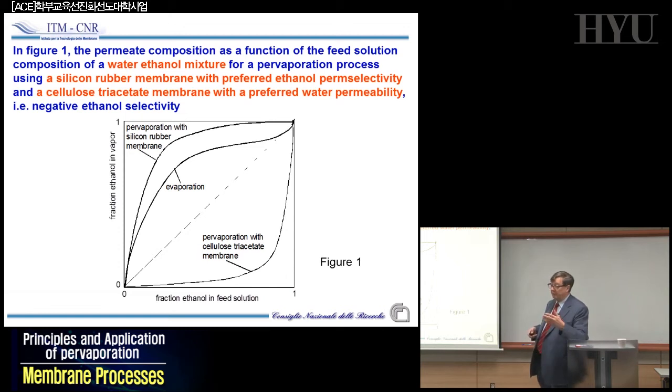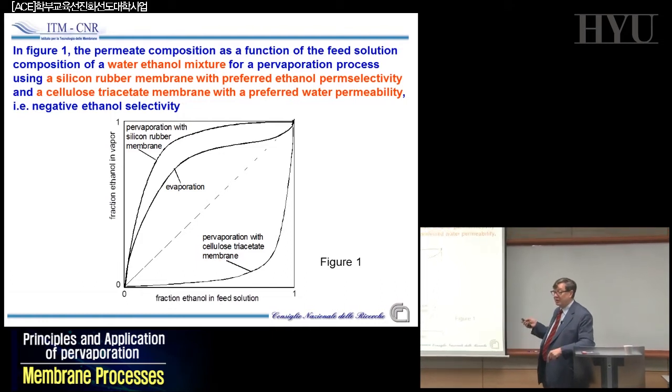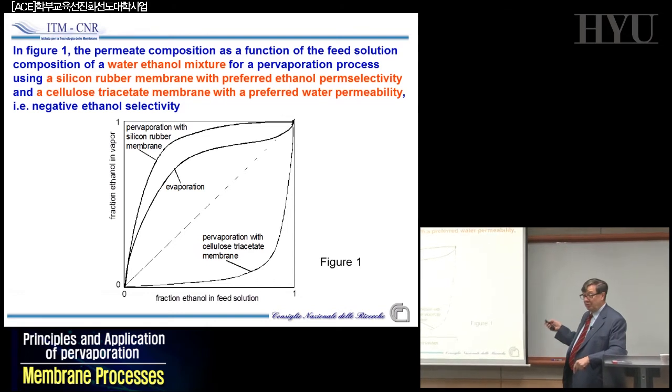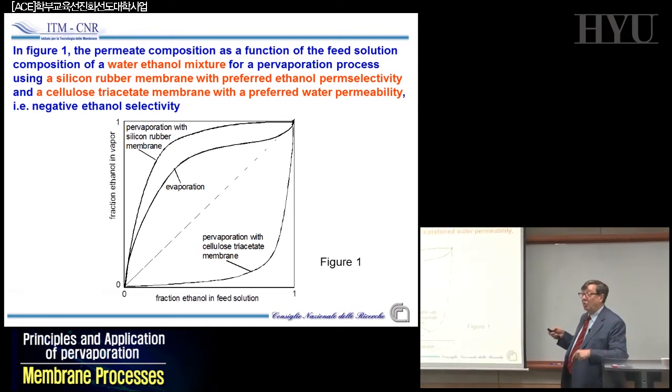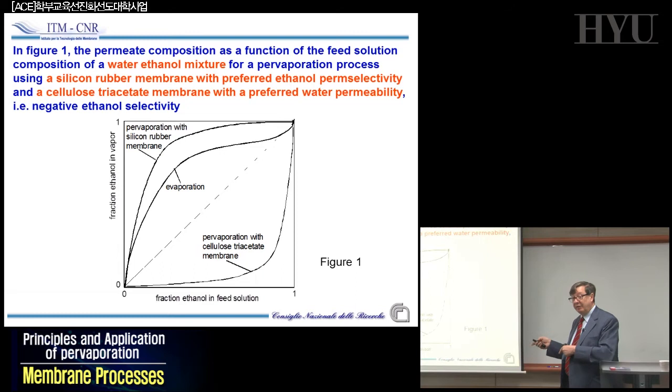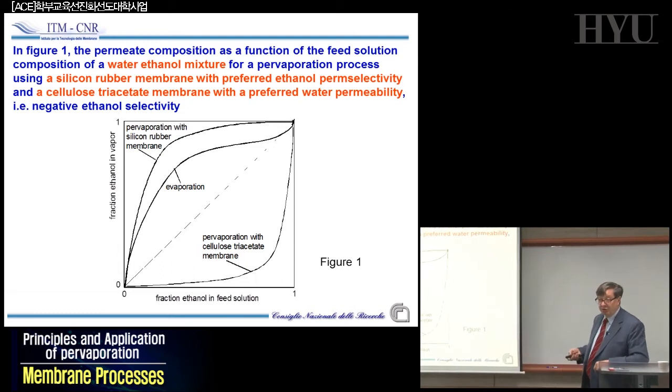So you are normally about 12–14% in alcohol, and after you have to remove as much as possible the water to arrive at a concentration approaching 99%. Any water in an engine will induce corrosion and will destroy the engine very quickly. So one of the first interests in pervaporation was to utilize this methodology to overcome the problem of the azeotrope that we have in the concentration of alcohol. And that's why you can find a lot of data in the literature of this kind.